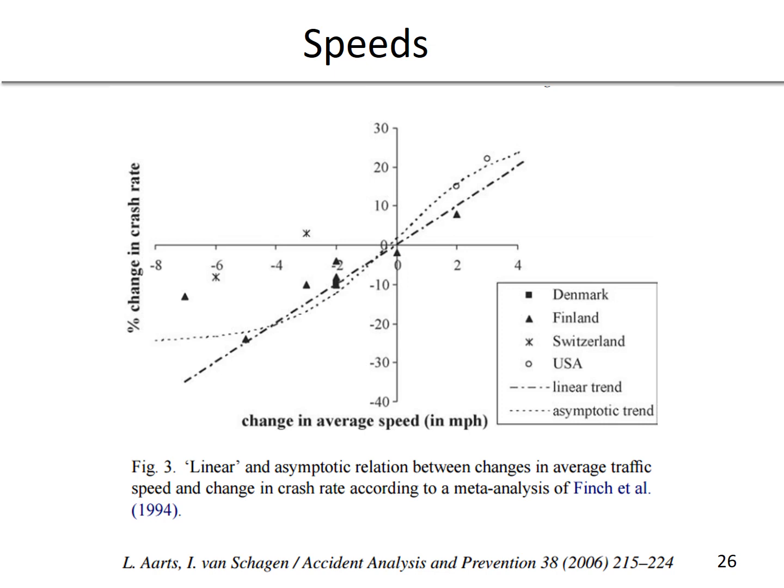If we can take an existing road and adjust that speed, particularly downward, if we can decrease the average speed of the vehicles on that roadway, we typically will see a decrease in the crash rate, as long as there's consistency among all drivers and we don't create an issue where some drivers are now driving faster and some are driving slower. Sometimes we'll have issues in those cases. But again, speeds are very important in the relationship with the crash rate.